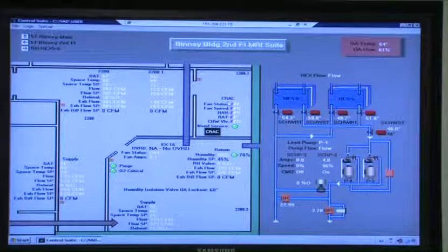And then we have a CRAC Liebert unit in here, and they're working on this long connection, I'm assuming. I have the 7th floor data online. Is there going to be a water on the floor sensor in there too? There is, there's 1 or 2 of them in that room. Can they show it on that graphic, like in the basement? Yep. Good idea. I think they're integral with the CRAC unit, right? Well, there's also one for the unit itself to shut it down. You don't monitor it, though. That would create a common alarm for your CRAC units. Yeah, it's part of the CRAC unit.